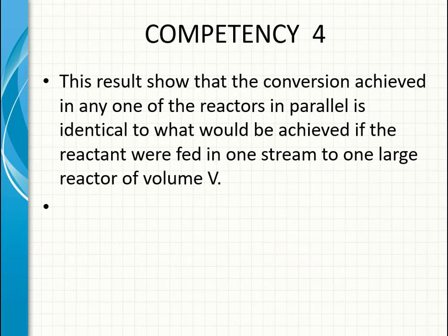This result shows that the conversion achieved in any of the reactors in parallel is identical to what would be achieved if the reactants were fed in one stream to one large reactor of volume V, which is the sum of all the individual volumes.